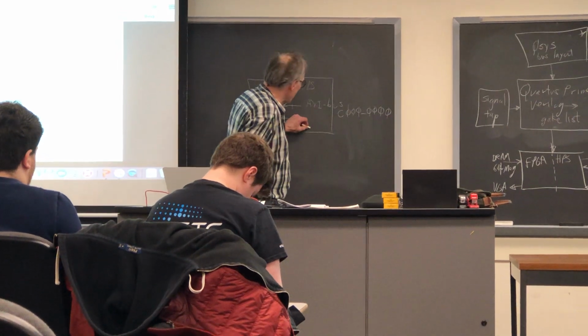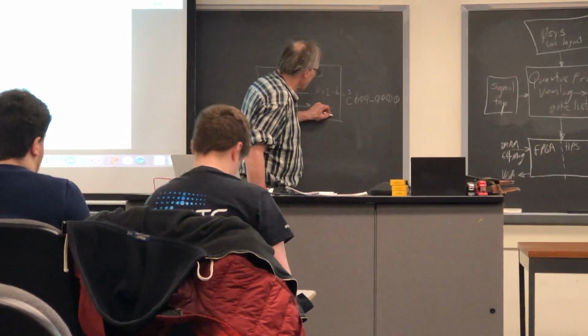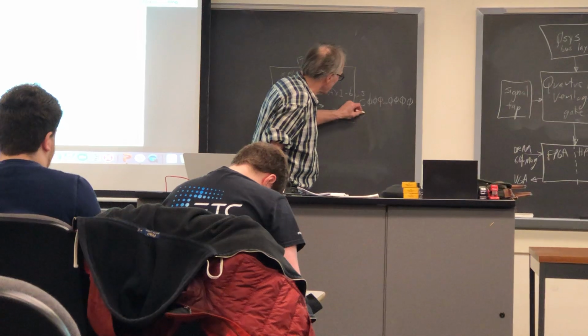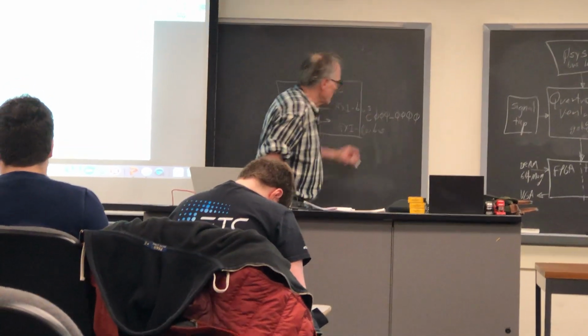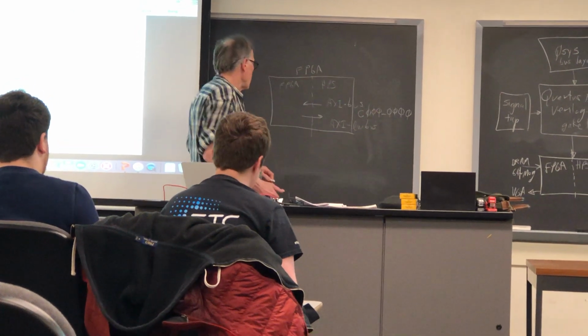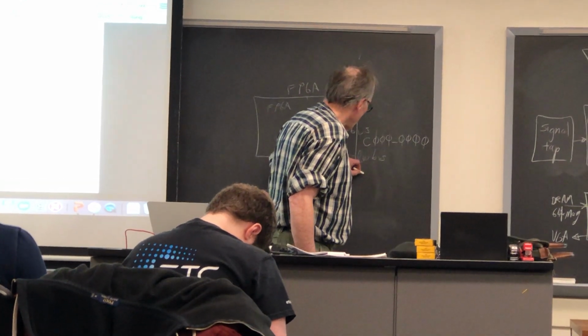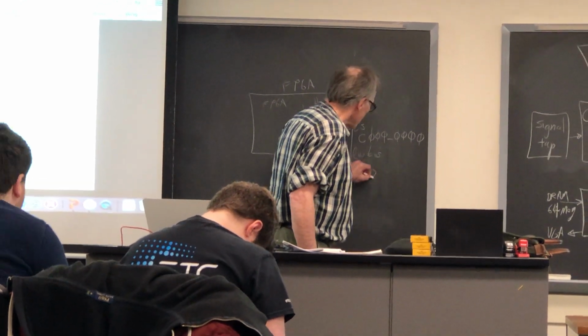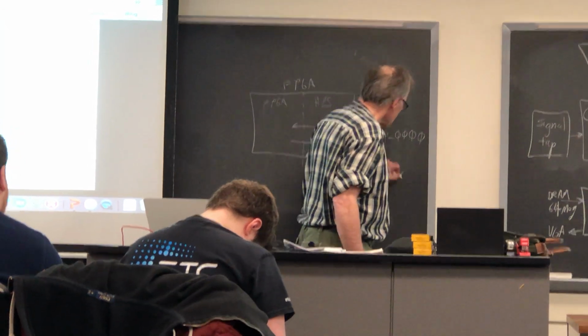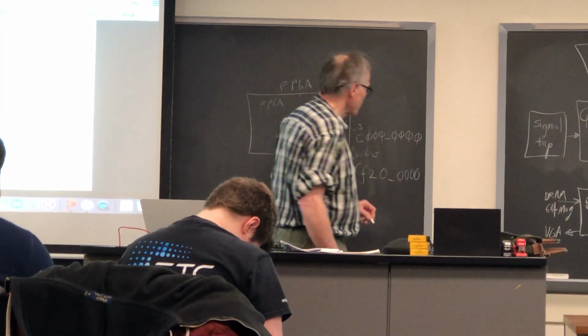And then there's the AXI lightweight bus, which is narrower and slower, which has a base address of FF200000.